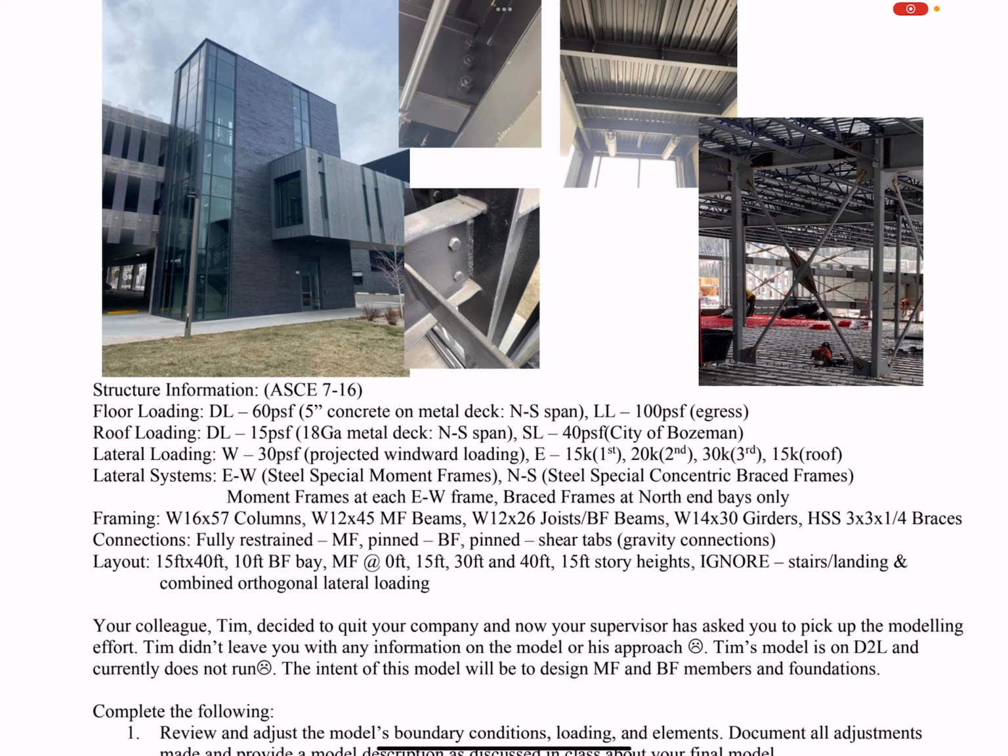So we have moment frames at each of the east-west frames. So in the VA model, I put in frames, right? So each one of them in the east-west direction. And then last bay, right? The brace frames are at the north end bays only. So out here, you can't see them. Obviously, they hide them. They're where the elevator are. Here in the elevator, both sides of you are special concentric brace frames down the whole height.